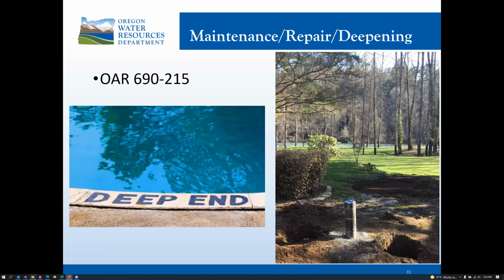Conversely, if the original well report does not detail this well meets minimum construction standards, that well can be deepened if that well is recased and resealed to meet current minimum construction standards during the deepening. Additionally, wells can be deepened that don't meet these standards through a special standards process, though the approval of that will be highly unlikely without having an original well report or being able to reconstruct the well to minimum standards.